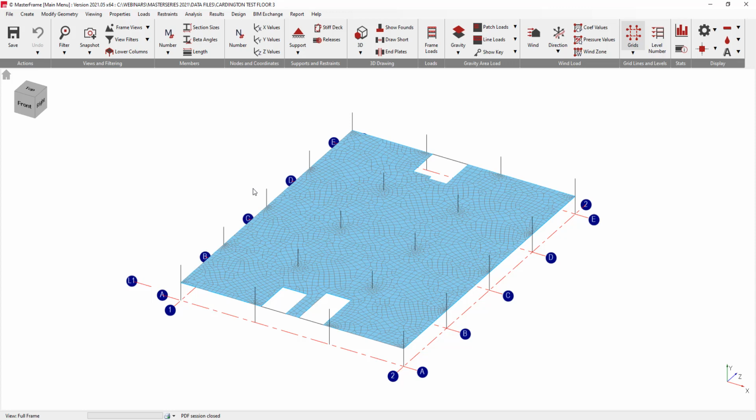So a range of -15 to +30% isn't unusual, as has been measured. Now, we're not suggesting that we don't have the data to say whether the MasterSeries range of error could be of that order of magnitude, but that range has come about from various calculation models and software over the years being compared with real-world deflections.